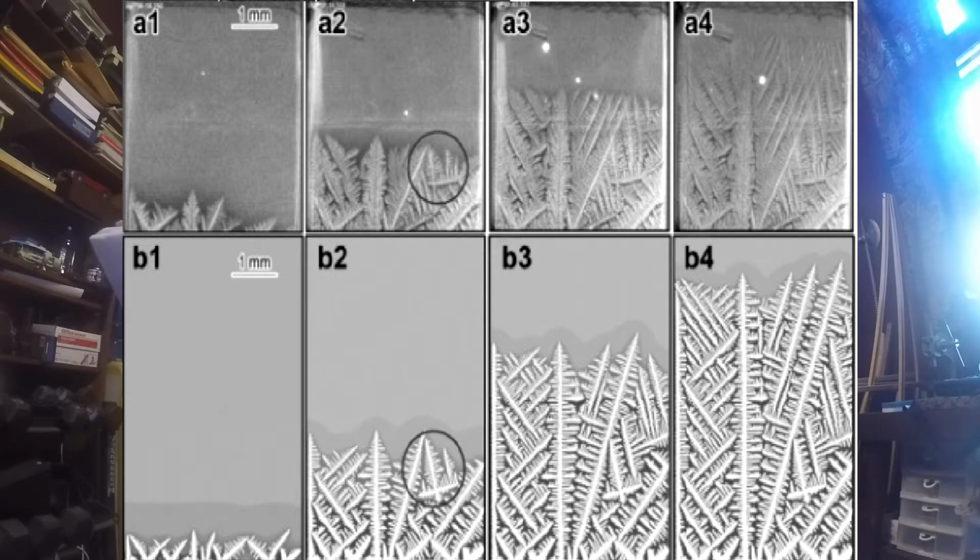The individual crystals will continue to grow until one runs into a nearby crystal, or until all of the molten metal has been used. When all of the molten metal has been used, gaps between crystals may form, the size and shape of which depend on the metal used and the rate at which the crystals are solidified.